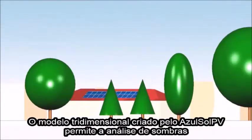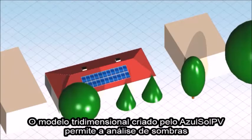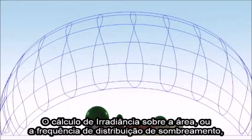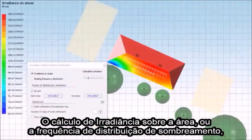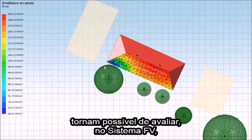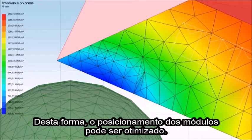The three-dimensional model created by AzulSol allows the analysis of the shadows on the PV system throughout the year at all hours of the day. The calculation of the irradiance on the area or the shading frequency distribution makes it possible to evaluate, on the photovoltaic system, the way in which the sun's radiation is lost due to the presence of obstacles near the system. In this way the positioning of the modules can be optimized.